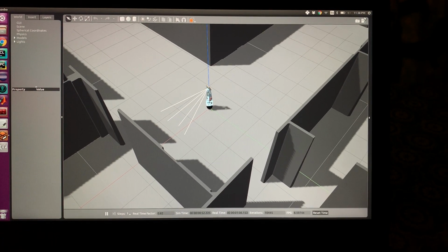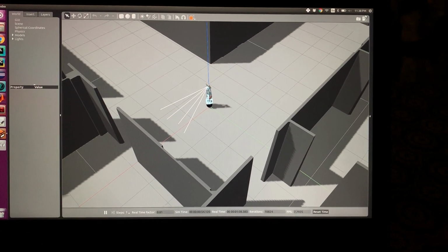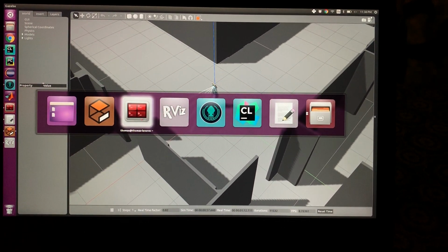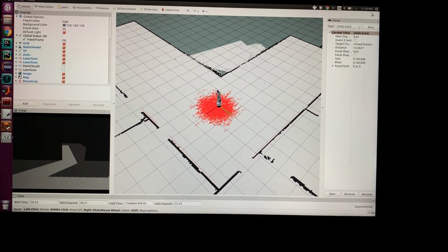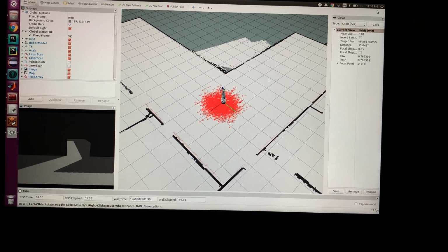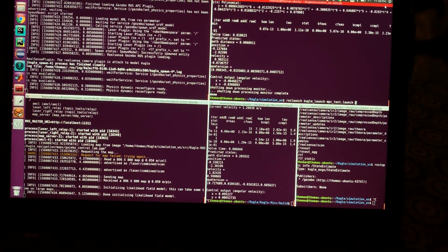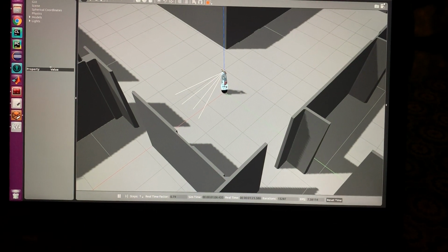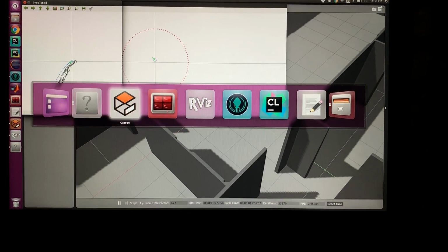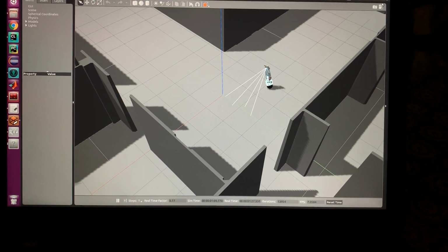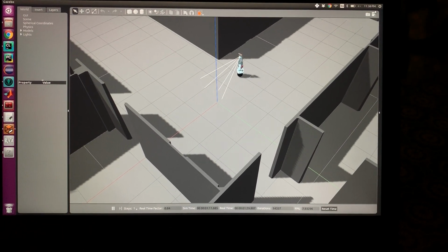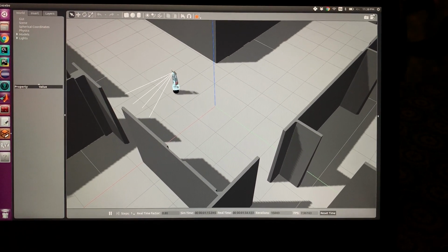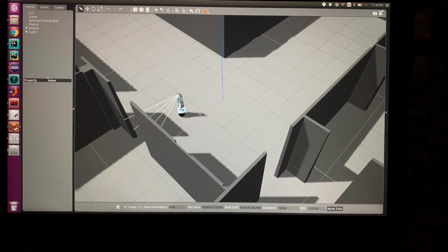MPC test has now been implemented and confirmed working with the simulation model, here shown the Gazebo simulation model, and the RViz view where we have the localization running. So now when we start the MPC, we will see the ball-bot starting to move around in a circle motion. And this is a pre-programmed static path that it's moving around.